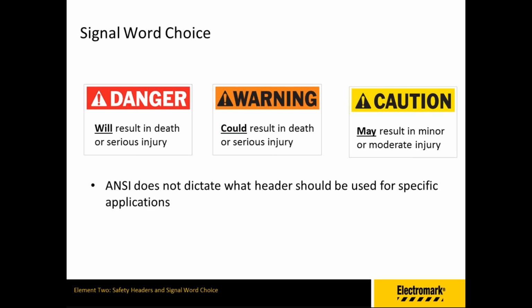Again, unfortunately, ANSI Z535 does not provide guidance towards specific physical location or equipment applications where a given hazard word may be appropriate. Rather, the standard only directs which hazard word should be used relevant to the level of hazard as determined by the user or poster of the sign. So it's really up to the utility to decide where danger should be used over warning, over caution, etc.